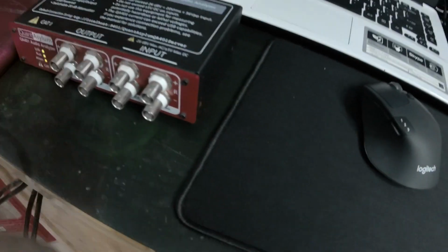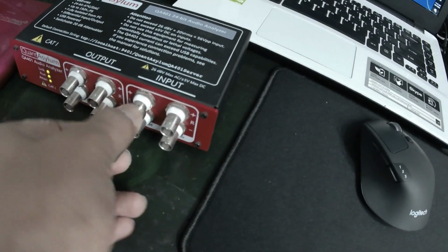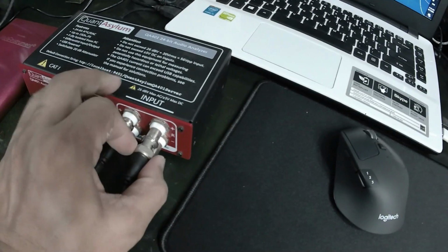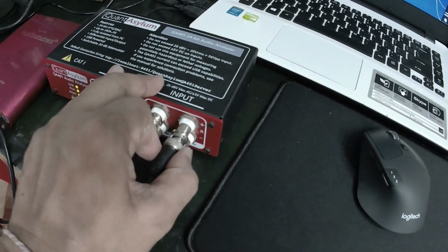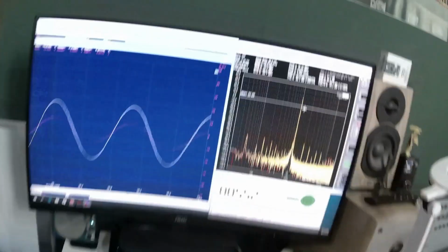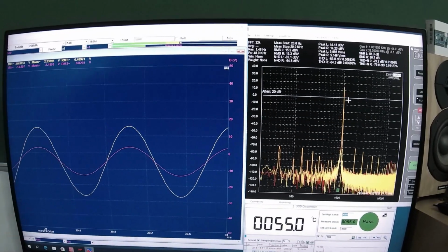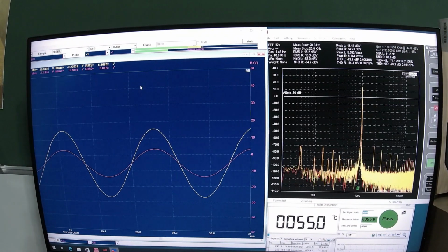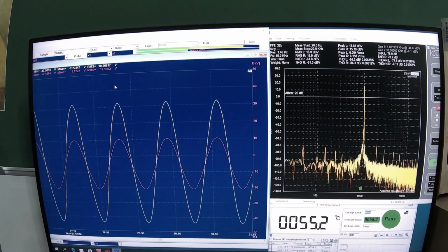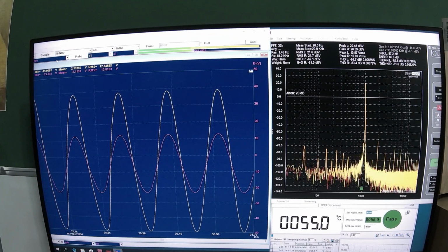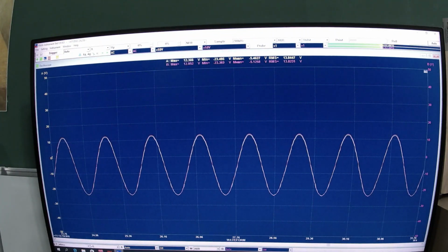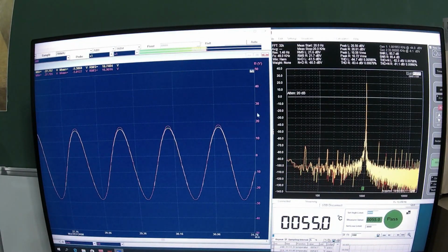Let's do some kind of experiment here. What I'm trying to say is that I'm going to make use of the QA401, and let's see the 20 volt RMS. No, that's 20 volt RMS output, the voltage swing at the 8 ohm speaker load. Let's see what the distortion is at 20 volt RMS output. We're going to monitor that one not to exceed that. That's 50 volt. Right, let me put that one into 50 volt. Okay, there you go.